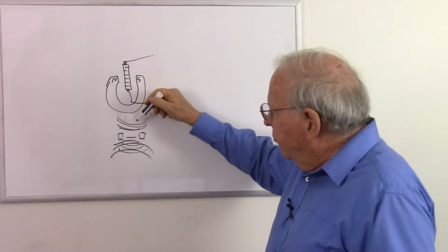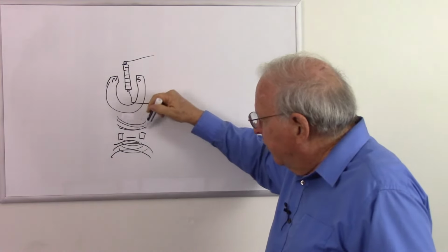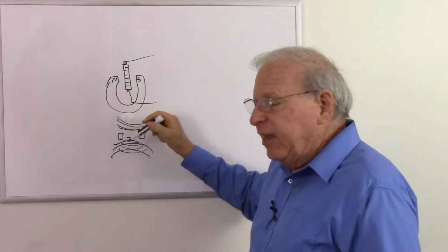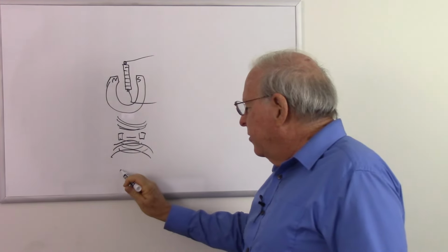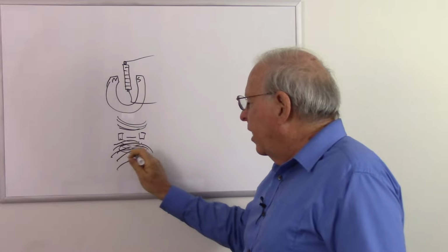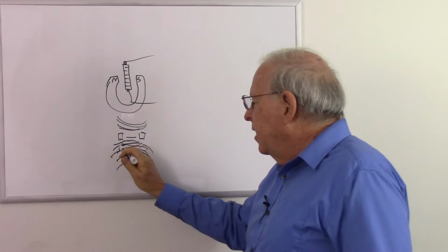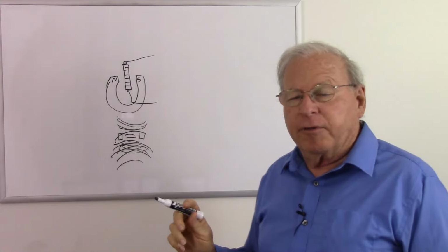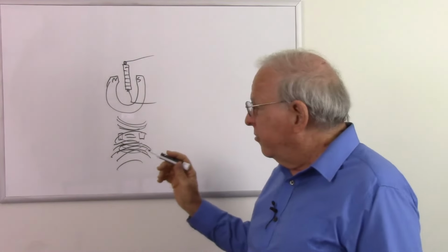Once again, it's not sensitive to the pressure because the pressure is pretty much the same on the front and back. So it's sensitive to the velocity of the air hitting it. And what happens if sound comes from the back? We get exactly the same thing. The ribbon is going to vibrate, sound is going to diffract around, and the pressure is going to be pretty much the same on both sides, so it's, once again, velocity sensitive.